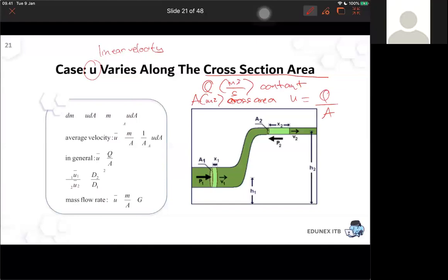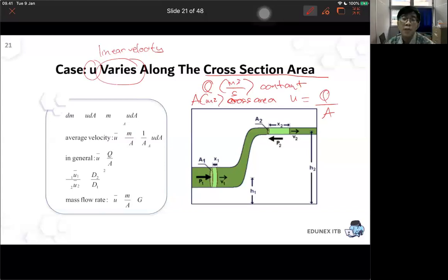So the velocity along the pipe will be the same, right, sir? Velocity is not. The volumetric flow rate along the pipe will be the same. But the linear velocity will vary. Okay, sir. And the area, you use the cross-sectional area, right, sir? Yes, the area is the cross-sectional area, the area of the circle. Do we take into account the cross-sectional area in which the fluid is in contact with the pipe, sir? Like just now, if it's not fully filled, sir? Oh, yes, of course.